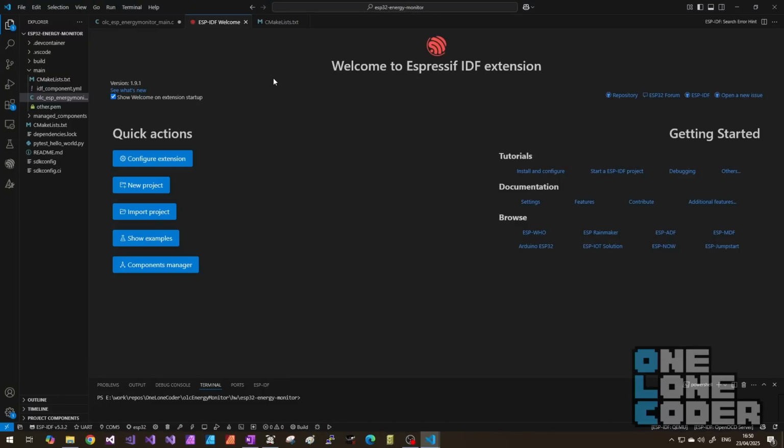Unusually today, I'm going to be programming in VS Code. It's like a lightweight cut down version of Visual Studio, but it's really just a text editor. However, it's becoming quite a popular tool for programmers and for manufacturers of little widgets like the ESP32 board, because they can design an extension which then sort of bundles a load of tools into this environment. And that's exactly what I'm going to do. By installing the Espressif IDF extension, it installs the appropriate tool chains to convert the C and C++ code that I'm going to write into the correct machine code that the ESP32 can run.